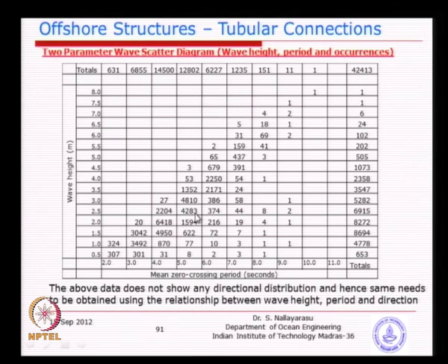If I just look at it myself without even doing calculation, I can say the effective wave height could be somewhere between 2 to 3 meters, and the wave period could be 5 to 6 seconds, somewhere there, because I know the numbers look in that order. Even if you do the calculation, you will be able to come to the conclusion, basically somewhere here. What it means, 5 to 6 seconds.